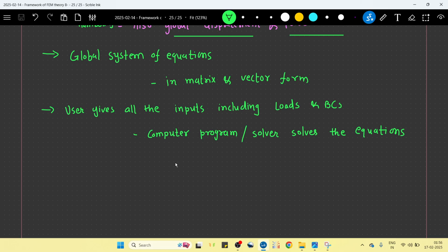Generally the software will have different linear solvers, and it will use that linear solver to solve the linear equations, which are nothing but Ax = b, if I am not wrong, this is the notation. This is nothing but Kx = F, our stiffness matrix, displacement and force vector. So these are linear equations.